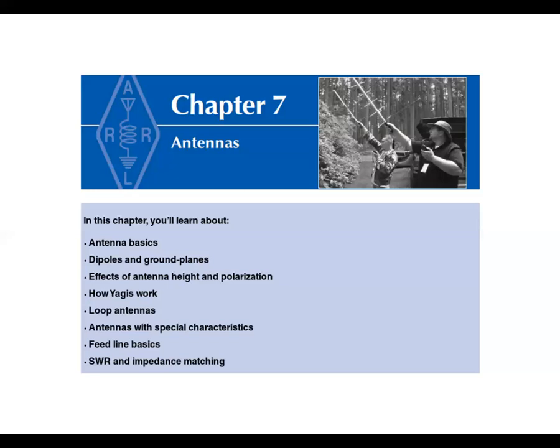There's a directional type of antenna called a Yagi. You can see the picture on this page. The guy's holding those two antennas. Those are Yagi antennas, characteristically a long beam with elements perpendicular to the beam. You see these a lot on radio towers hams have, and that particular application that they're doing there is satellite communication, where they sweep the sky with that antenna as the satellite passes, and do the communications.